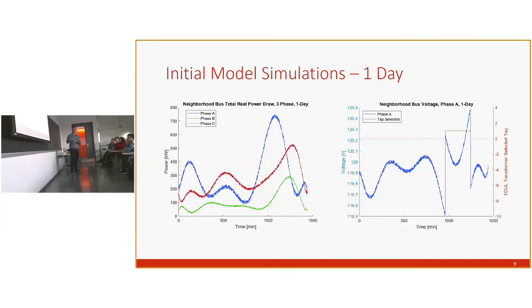So looking on the right side, we see just the A phase voltage at the tap changing transformer. The voltage should be nominally 120 volts. We see as the load increases, the voltage here drops, and it seems it's very close to 120 volts over here, and then it drops down, and it really seems to get out of our acceptable zone. We see the red line, the tap changes. We were at tap 0 at the center tap, and we change up to the first tap. The voltage jumps back up here closer to the 120 volt mark. The load continues up until we see a spike in voltage, where the tap then returns back to center tap and the voltage drops down closer. So it's doing its regulation job as expected.